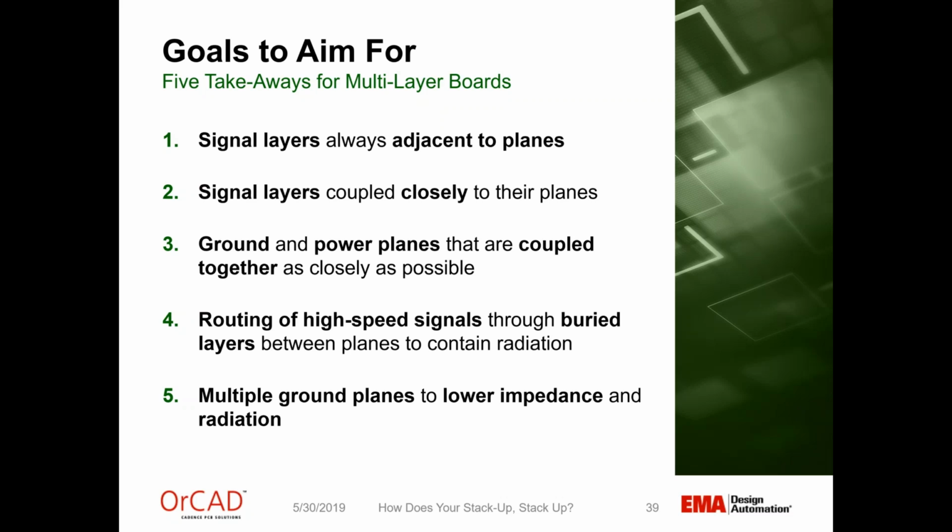Signal layers should be coupled closely to their power plane. So you want those connections, the distance to be as close as you possibly can. And same thing for power and ground planes. You want them coupled together as closely as possible.